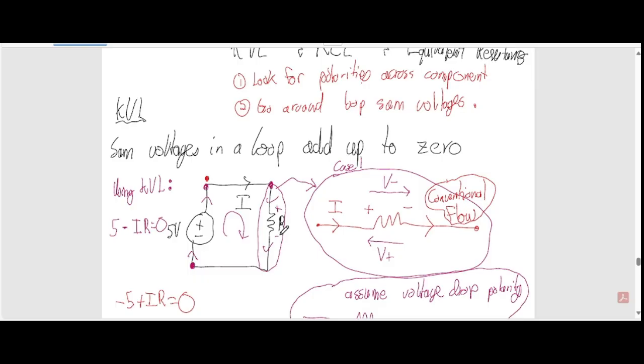And remember this little diagram I showed you with the current, the resistor and the polarity. When you're in the direction of the current, there's plus to minus across the resistor, so that's a voltage drop. And obviously in the opposite direction, against the direction of the current, is a voltage rise. That makes sense?